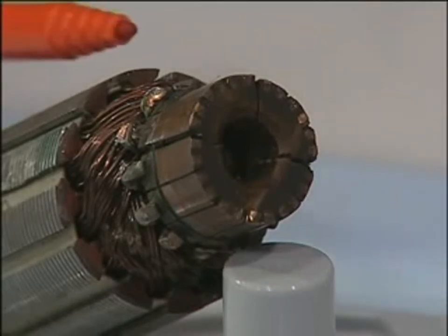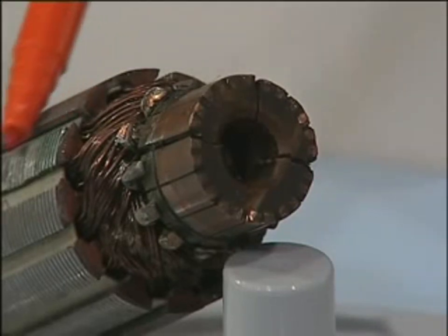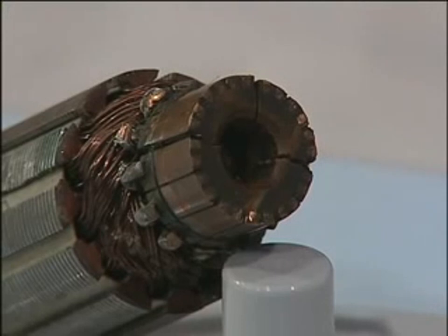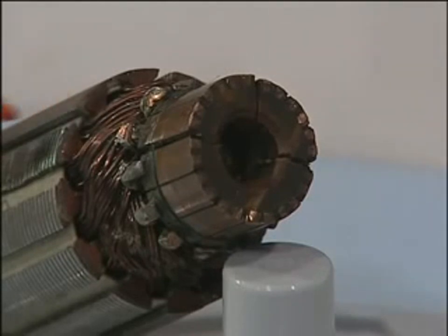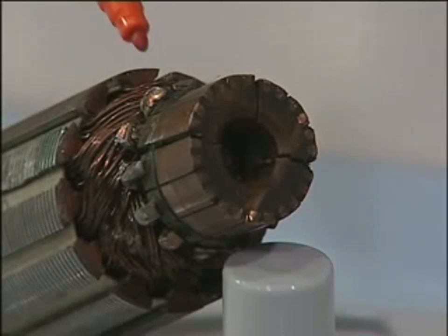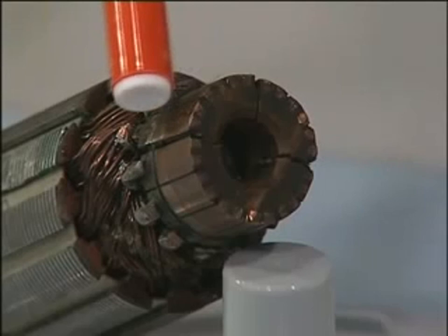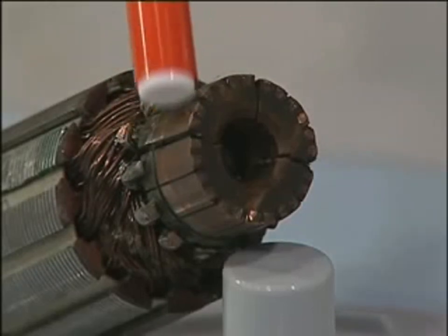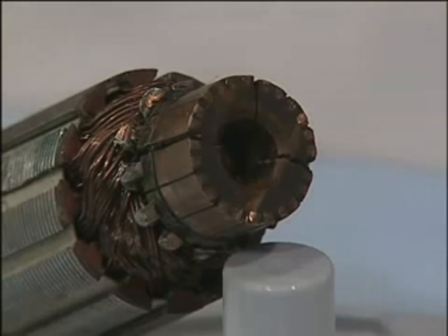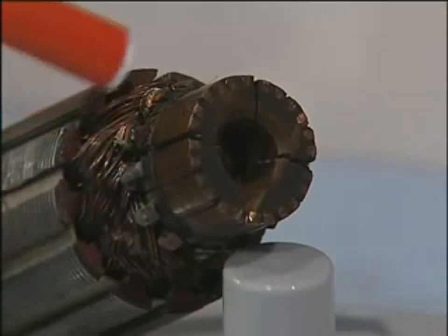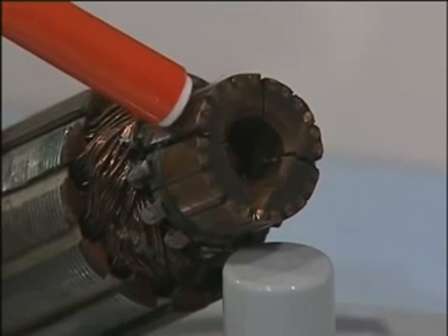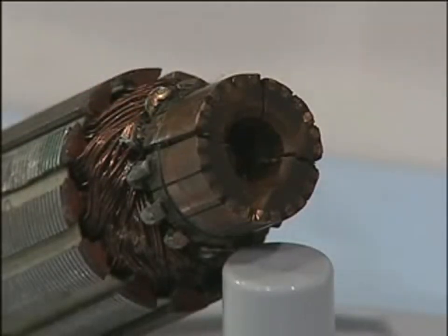So the armature consists of the core, and that is also laminated here, again because, as we were explaining during the time of the transformers, the laminations are used to reduce the eddy current losses. This portion is the coil ends which are joined to the commutator segments. The brushes will come in contact at this copper surface of the commutator segments, like that. It will be spring loaded. We will have a look at that in a different machine.